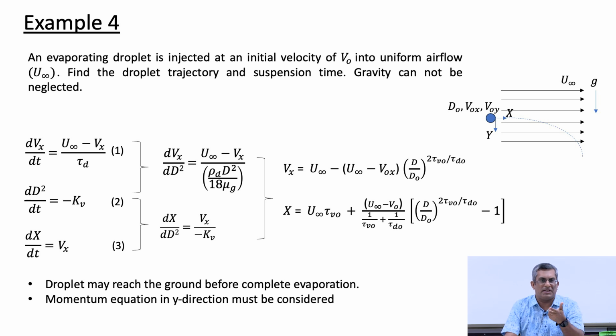is very small and it quickly adjusts, then what will happen is that the terminal velocity is always retained, but the terminal velocity itself reduces with particle size, because your particle size itself reduces. So, the terminal velocity will also reduce. Terminal velocity is not a constant because particle size is not a constant. Okay. So, when you solve this, especially numerically, you may encounter this situation. So, at that time you have to implement such model. Okay.